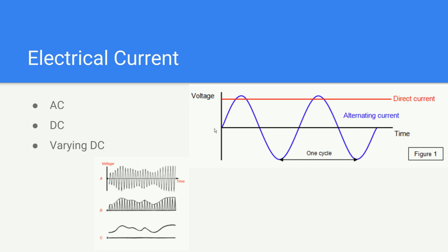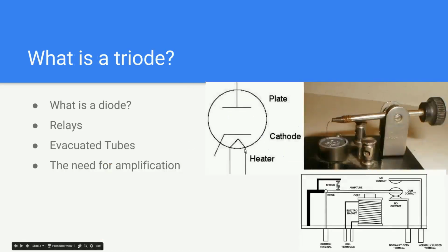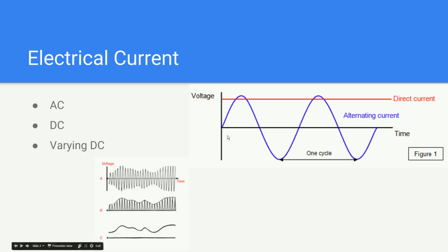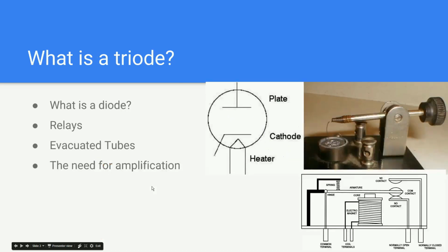That means that 550,000 times a second, there's a waveform going through the air, like that. What a diode allows you to do is cut that in half and play it through, say, an earphone. Because if you didn't, then each of these phases would cancel each other out, and you would actually hear nothing. But if you use a diode and cut off half of that, then you have something where it can create vibrations and sound.